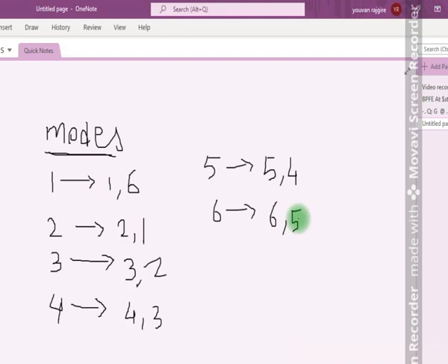Likewise, there are six different modes of operation that will take place. This is when we want to perform the operation based on 120-degree conduction mode. During that, one switch from the upper limb and one switch from the lower limb will be conducting at a time.